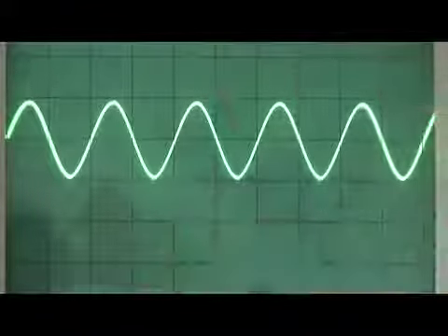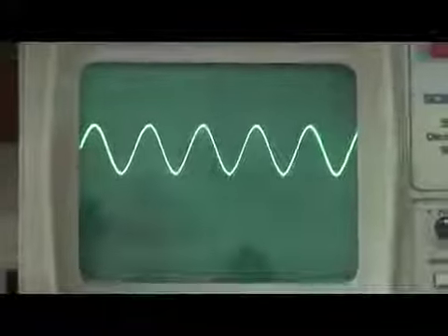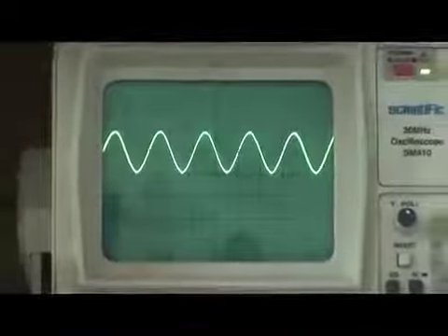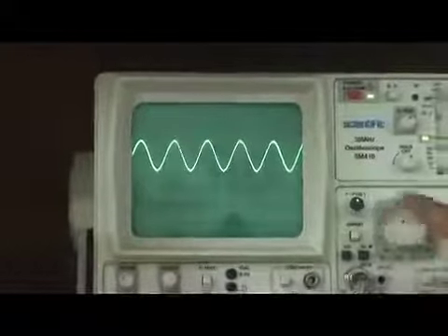So it is 1.9 blocks that it is taking for this amplitude. That 1.9 into, you can see here where this knob lies, it lies at 1. So 1.9 into 1 is how much? 1.9. And what will be the unit? The unit depends on where this range lies.